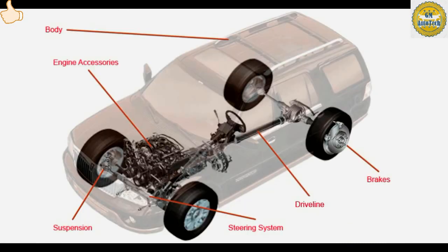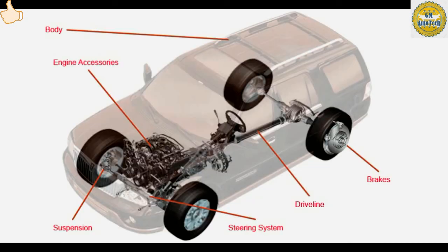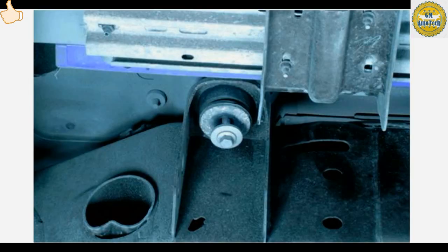Noises from engine accessories can be caused by belts that are incorrectly installed, contaminated, incorrectly adjusted, worn, or glazed. An engine accessory with a defective bearing, pulley, or gear may also cause noise. Be sure to thoroughly inspect all engine accessories when diagnosing the root cause of a noise concern. Loose bolts, broken pinch welds, and damaged body mounts can all cause body-related noise, such as rattles or clunks. Inspect for damaged or improperly torqued components.